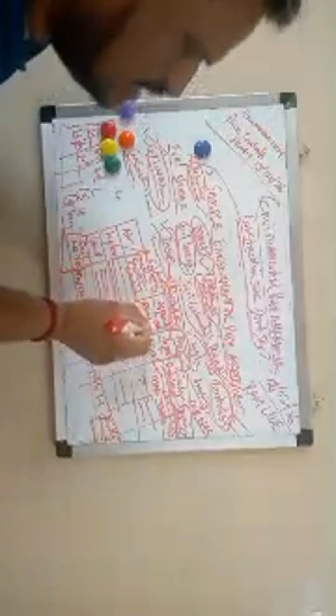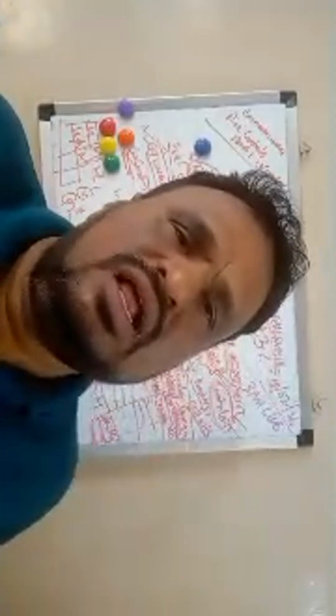The same thing applies to all the activities in your construction site: you have to table them. For those activities, what will be the environmental aspect, the environmental impact, the risk level, high, low, or medium, then the controls. This tabulation is very important. That is called the environmental risk assessment. You have to produce this environmental risk assessment and keep it ready for auditing, legal purposes, any client or legal audit; you have to show it to them.